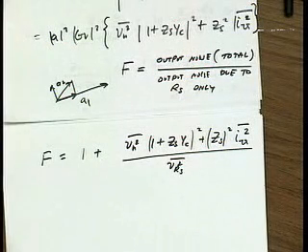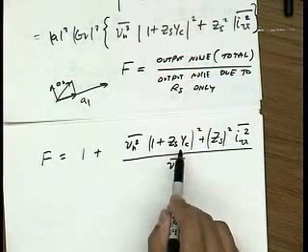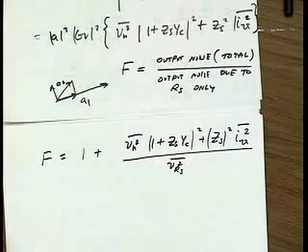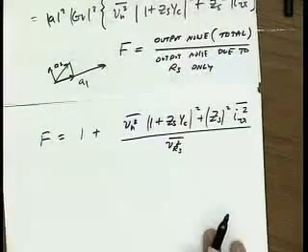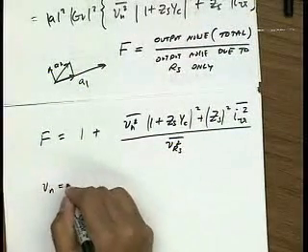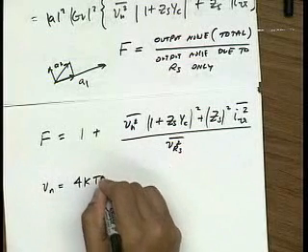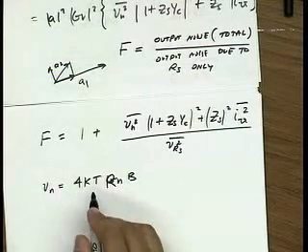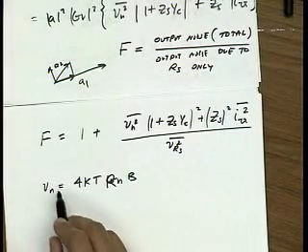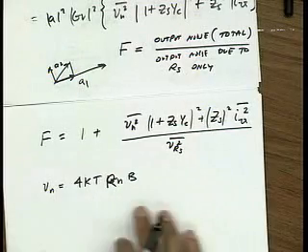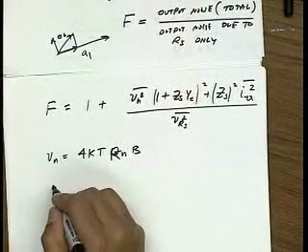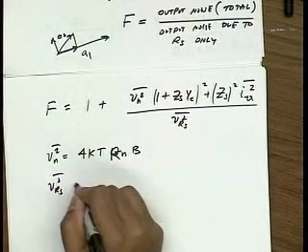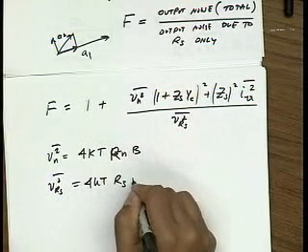Now if you look back to last lecture, if you just make the correlation Yc equal to 0, totally uncorrelated, you get the same result that we got last lecture. Okay. All right, now it's just like last lecture, we're going to give some equivalent resistances. So I'm going to call it Rn. I'm just going to assume that the noise Vn is generated by some resistance. I'm calling it Rn here. Noise, of course, due to Rs is 4kT Rs b.